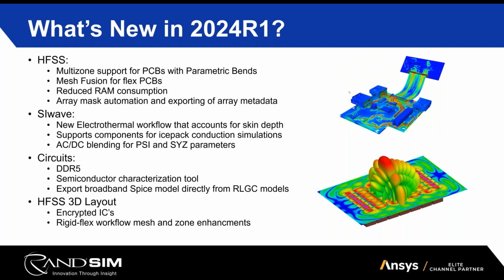On the circuits realm, when we're talking about signal integrity, we've updated to have DDR5 details associated, as well as a semiconductor characterization tool. And then inside of HFSS 3D Layout, we already had some encrypted models, but we now have built it off into having encrypted ICs as well as building additionally onto that rigid flex PCB workflow and enhancements. That's a very common area that we've seen. More and more boards in the industry are becoming a rigid flex type, whether that be from form factor or size constraints. So Ansys is continually making improvements and investments in that space on the electronics side as well.